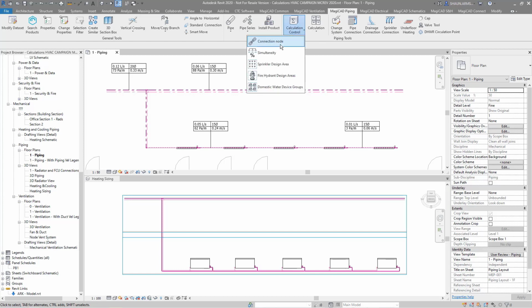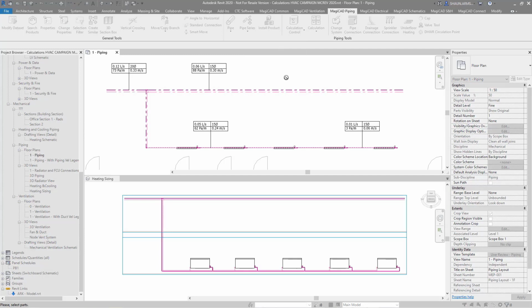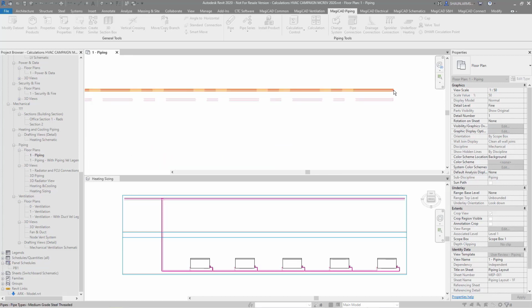These are in calculation control, and what these are used for are future use in buildings, basically adding a load and a pressure onto a system so that we can allow for it within our sizing, but we might not have the architect's layout set out correctly. Or this could be for a kitchen fit out, for example, and the kitchen's done by a specialist. So what we do is cap our pipes, ducts off into the ceiling, but we need to allow for that load.